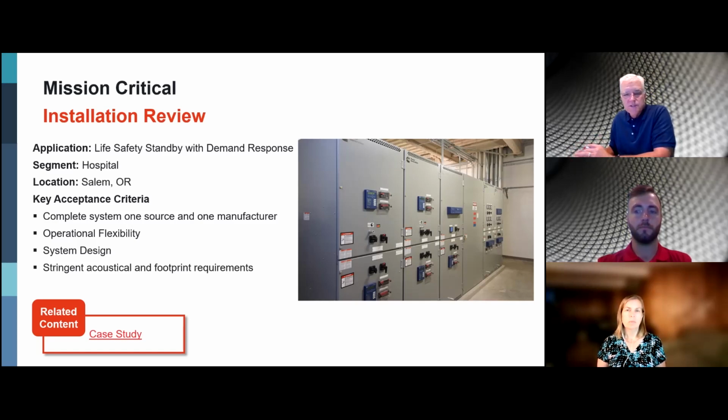To accomplish this, Oregon State Hospital has 2 switchgear lineups, one for the hospital, one for the grid. The hospital can apply their standby procedures in normal blackout situations. PGE can also monitor and call for the standby generators to the grid in critical times of need. So it creates a win-win scenario for both.